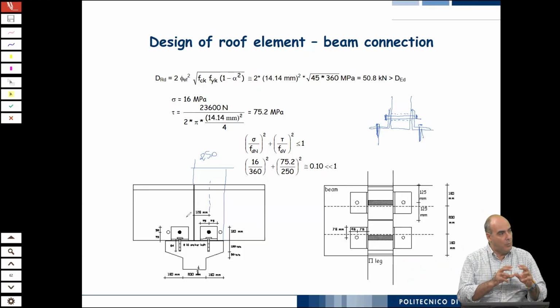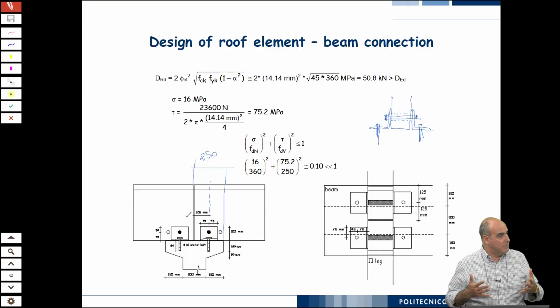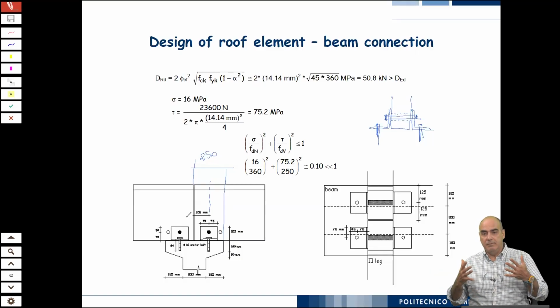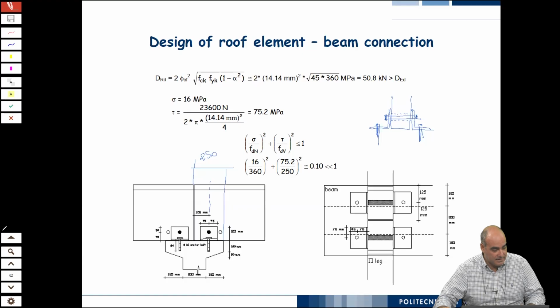No, when you go with the sizes that you have and the fact that you have to guarantee a minimum of concrete around, it's not that much. So this is a very important reality exercise that you have to make when you design the connections. Because since in our schemes we draw reinforcement as small circles, it seems that we have infinite space, but it cannot be like that.